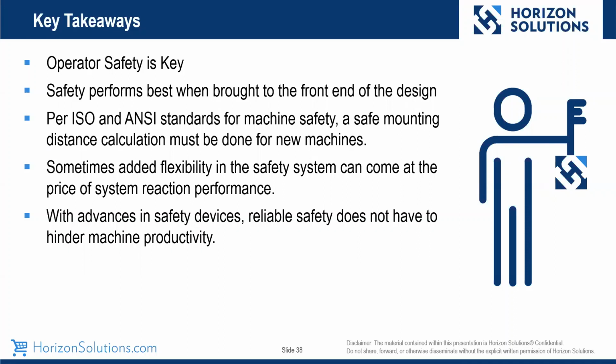To that point, safety always performs best when it's brought to the front end of the design. Safety always works best when you design it in rather than put it on retroactively. Per the ISO and ANSI standards for machine safety, a safe mounting distance calculation must be done when mounting any presence sensing device for a new machine.